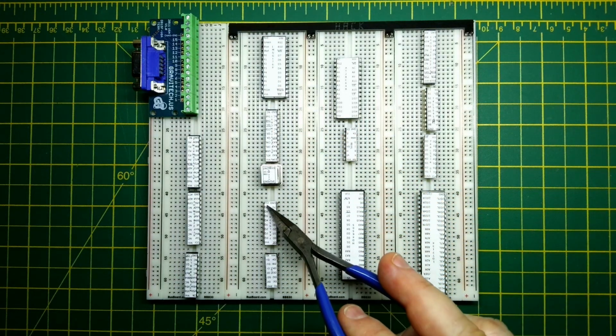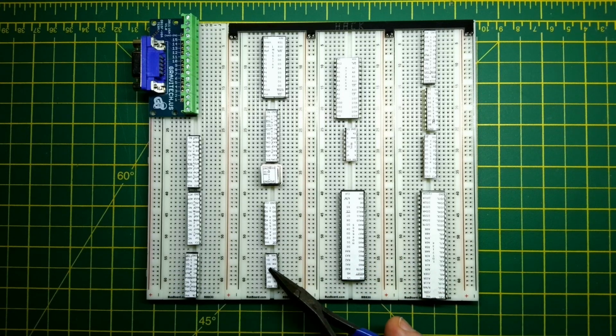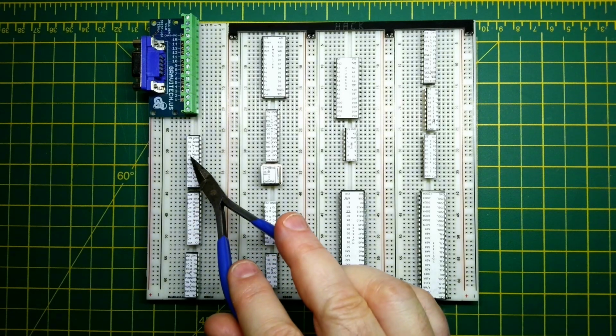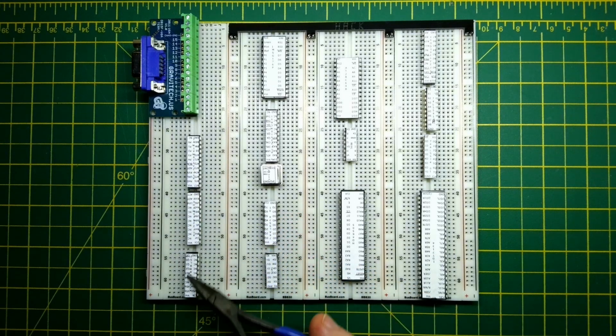This is our attribute latch. Then this is the CRT control, and then we've got the video out PLD, the attribute PLD, and then I had to move this over to here. So this is the blink clock PLD as well. So I think this layout will work fairly well. So I'm going to take the rest of these chips out. I just wanted to make sure that everything would fit where I was going to put them.